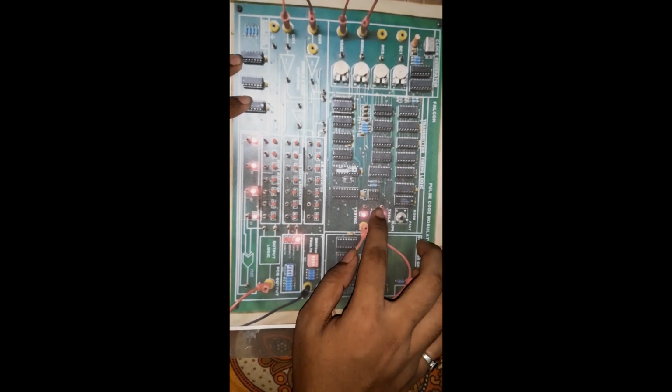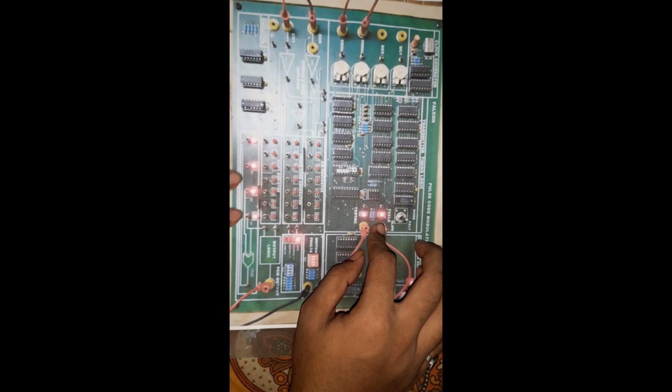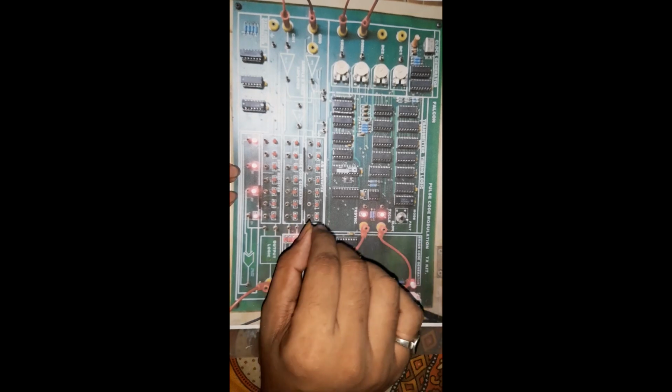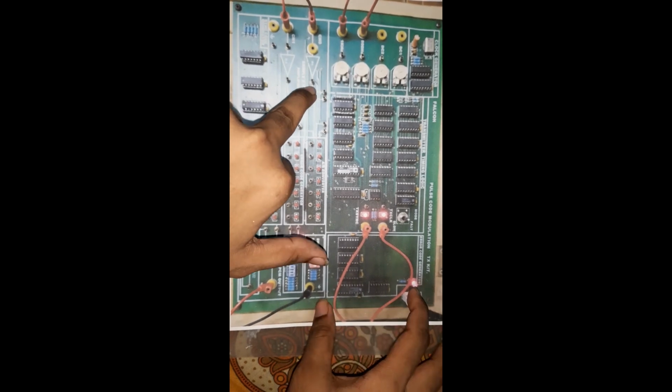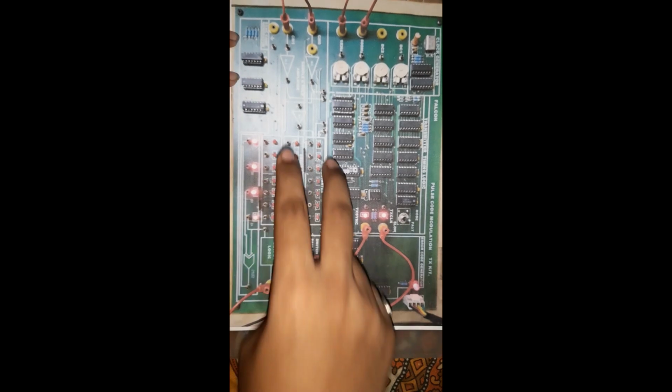So according to the blinking and the combinations of these 4 LEDs, you have to note down the 4 bits continuously, and keep noting down those bits until the same bit patterns are generated again. That means after 16 combinations you will see the same bit patterns; you have written 16 numbers of 4 bits, and you will see that the data are repeating again.